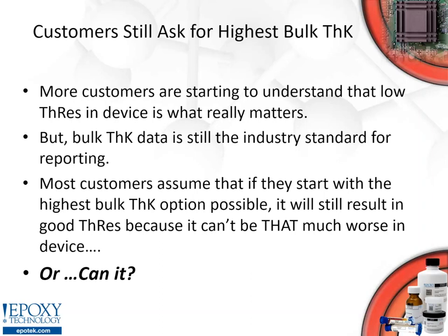As we've gotten further and further into our understanding of thermal conductivity, we've realized that the in-device thermal resistance is what really matters to customers. But that thermal conductivity is what is tested in the industry. Most customers assume that a high thermal conductivity on the datasheet is going to mean good low resistance in their part. But as we've shown, that requires an ideal bond line, and that's not always the case.